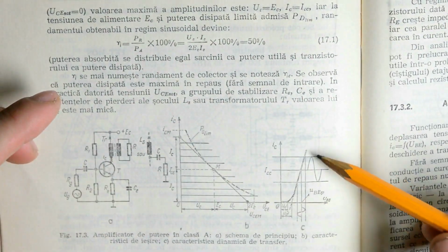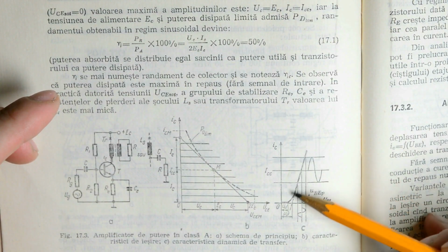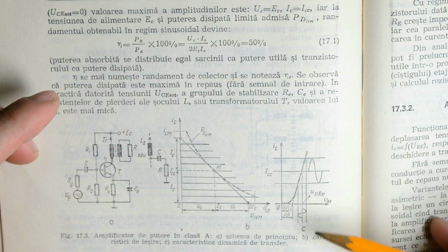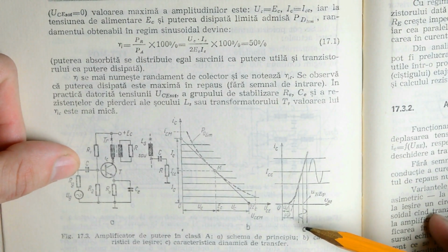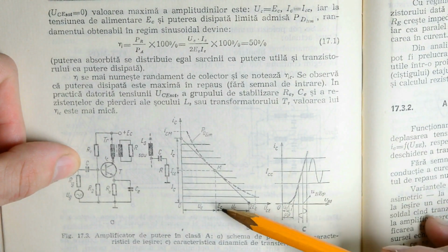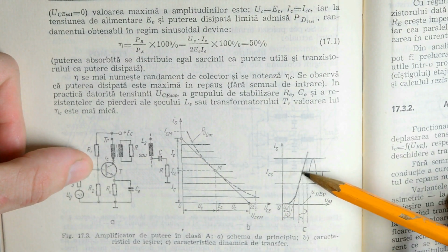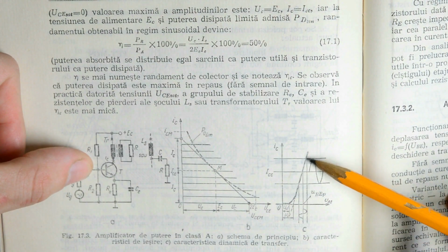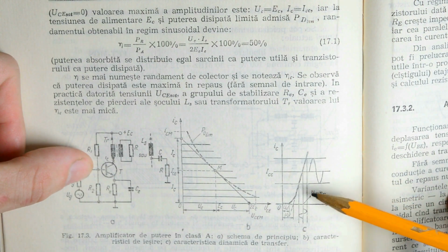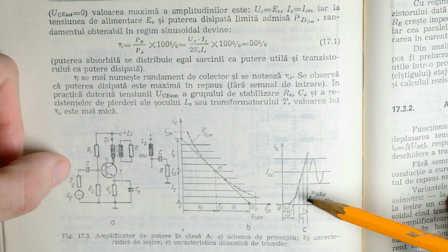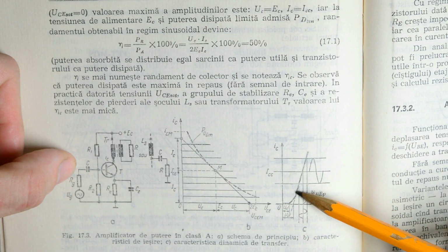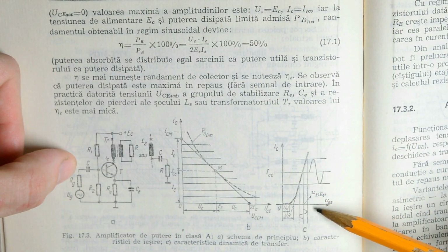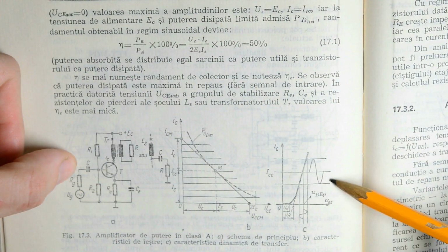But to keep the transistor in the amplifier mode, we need to keep it in the active region. Especially if we look at this graph, we need to keep it in the linear amplification region. Therefore, to keep the transistor in a class A type of amplifier, we need to bias it with a certain signal so that it stays in the middle of this linear portion. So even if you don't have a signal, there will be current passing through the transistor. Now the signal that you are adding will just move our bias point left and right on this curve, giving us our amplified output signal.